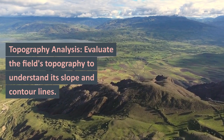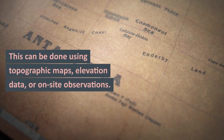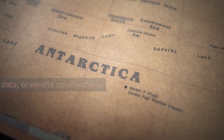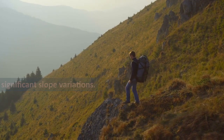Topography analysis. Evaluate the field's topography to understand its slope and contour lines. This can be done using topographic maps, elevation data, or on-site observations. Identify any high points, low points, or areas with significant slope variations.